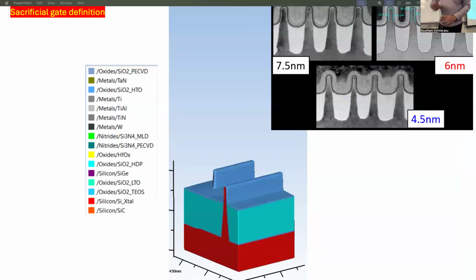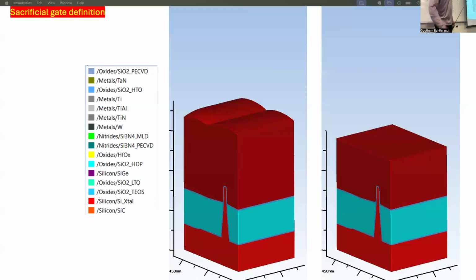Yeah. So next, remember, always when you have silicon exposed, you never want silicon to be exposed. It's not a good idea. So you always protect it with some barriers. In this case, it's some oxide, some ALD oxide barrier. And now that you have this, you're going to create your actual replacement gate process, right?